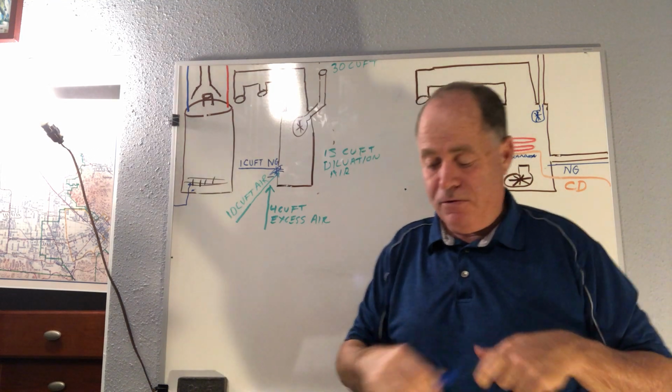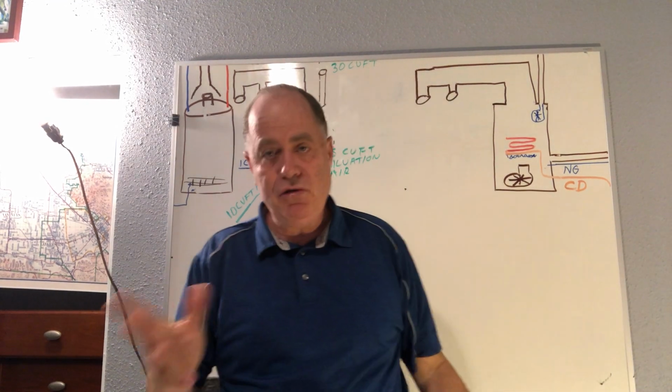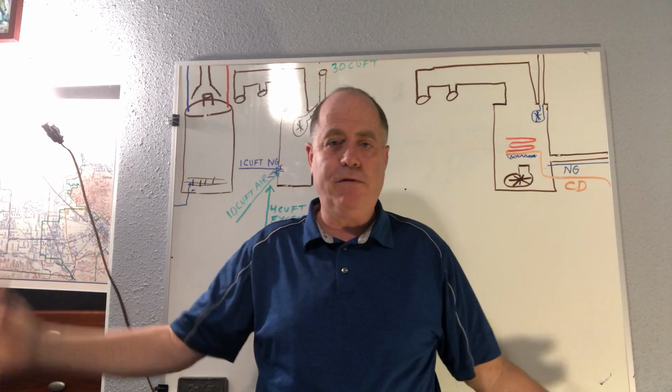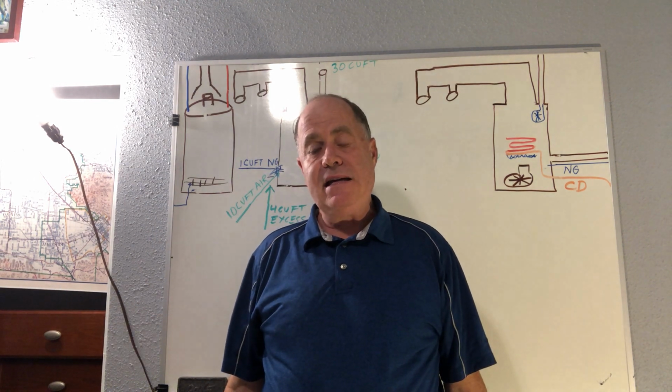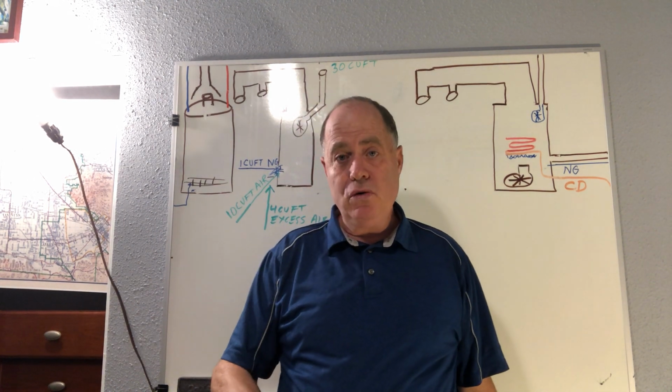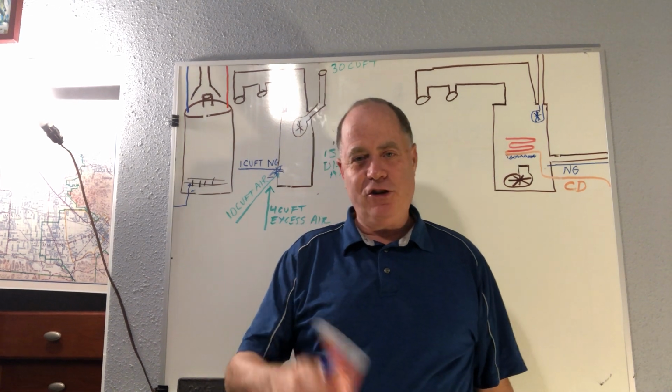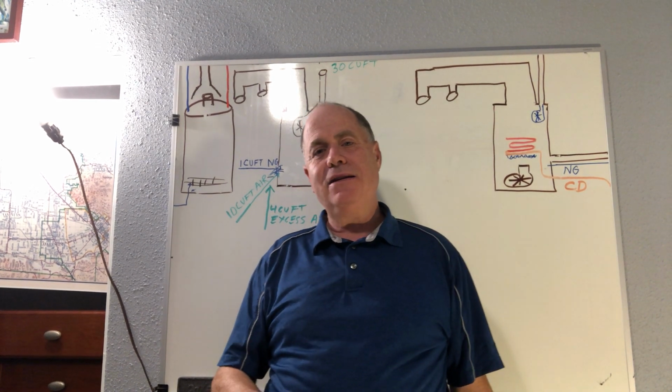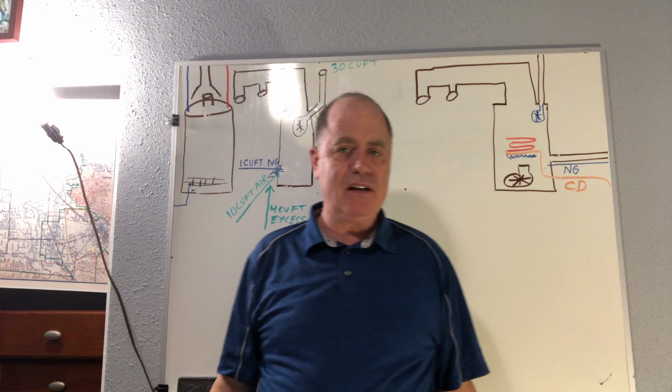They're not even giving people the chance to do that. By the way, when you do that, what happens to a furnace that doesn't have enough air is the flame goes from blue to orange. And when you see an orange flame, you have carbon monoxide.